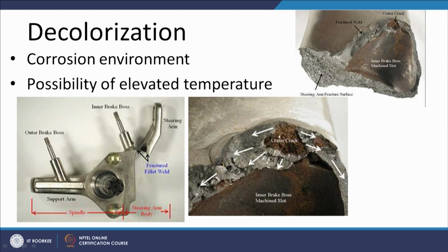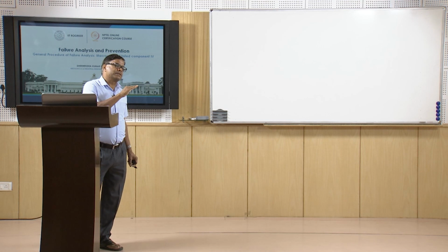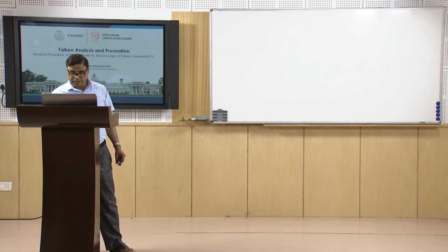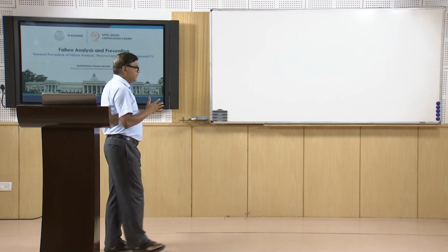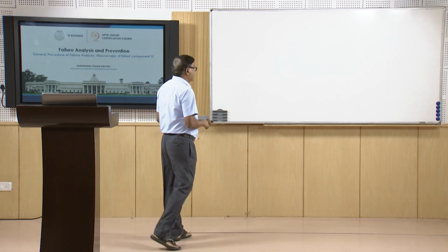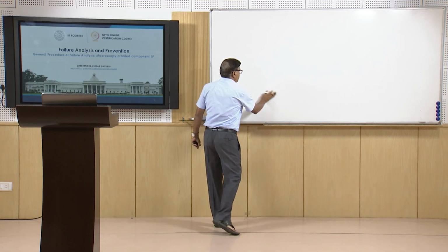So, it will be indicating that the surface was exposed to corrosive or environmental conditions for a certain period of time with the change of color. If there is some freshly fractured surface, then it will be bright, shining and reflective, meaning bright in color, and it will not be dull.